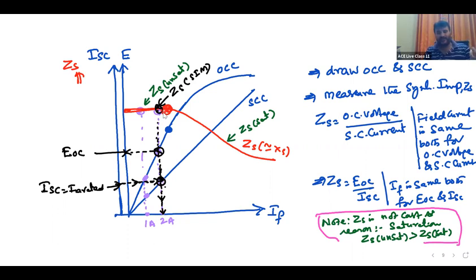Field poles are active because under short circuit condition, armature reaction is purely demagnetizing. Therefore, there is no saturation. So ZS is measured in the unsaturated portion.